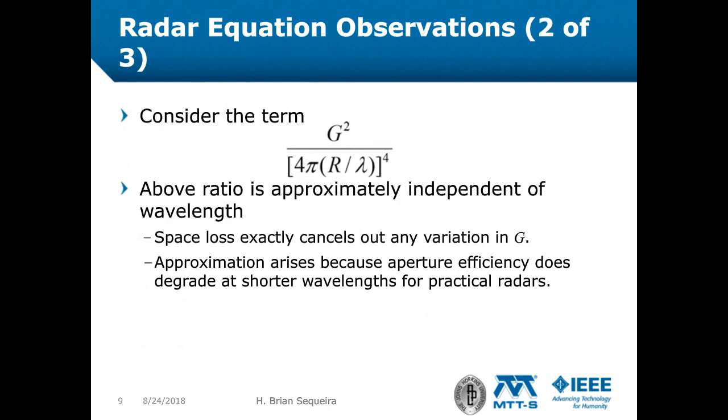It is interesting to note that if one took an existing radar and merely operated it at higher frequency or shorter wavelength, the gain of the antenna would increase, but so would the spreading loss by the same factor. So there's no apparent benefit to operating a given radar at a higher frequency than for which it was designed. In fact, performance would actually diminish because of higher losses due to other factors such as pointing and weather, as well as tolerances on surface shapes and placement of feed optics to retain the same illumination as at the previously longer wavelengths.